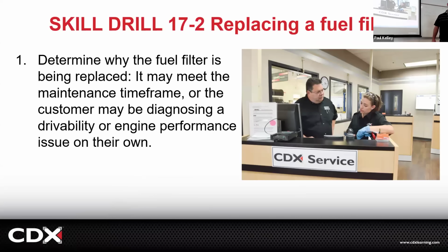All right, if we're into a fuel filter, why is it needed? Maybe because it's due on the miles, right? So if you want to sell a customer something, you got to have a reason. Why are you going to sell spark plugs? Maybe they're due on mileage. Same with a fuel filter. Maybe you're selling spark plugs because you took them out, inspected them, and the gap was off. Maybe you're selling spark plugs because you diagnosed that it's part of their misfire, right?